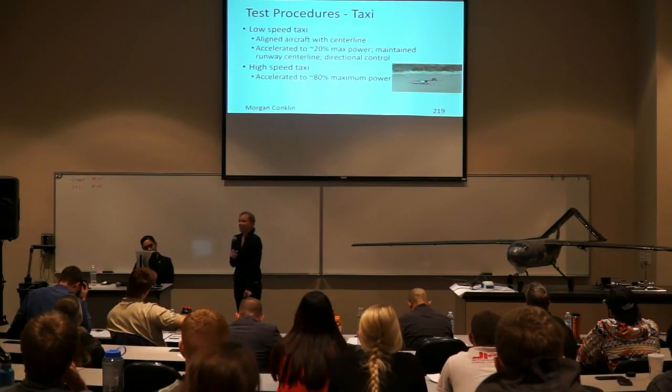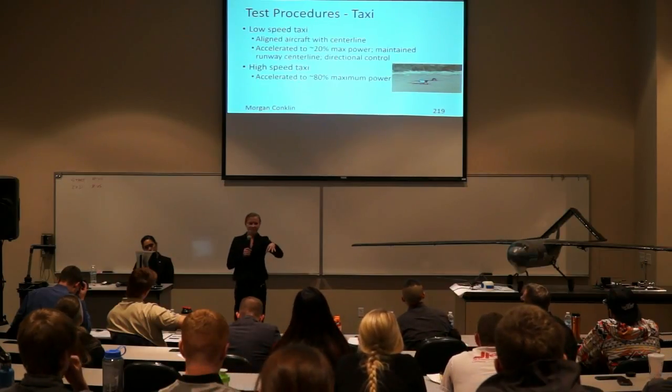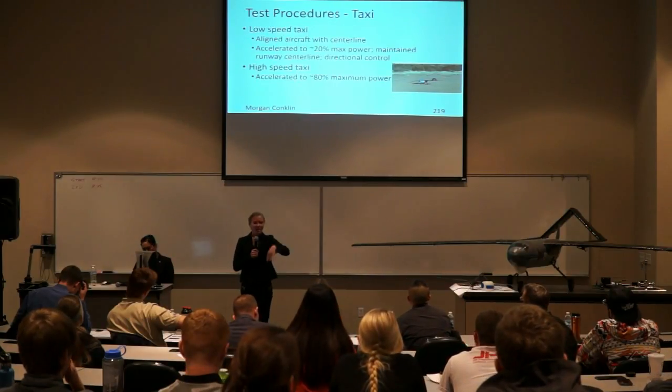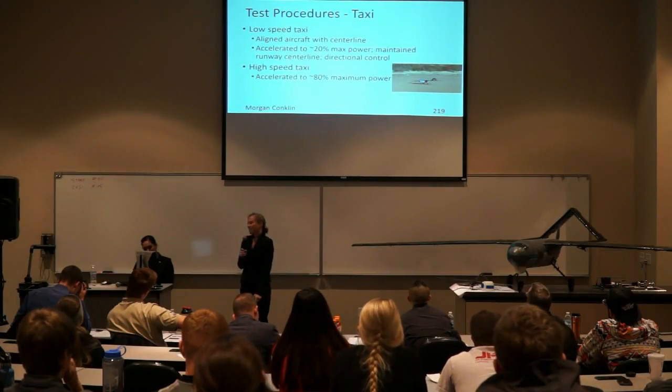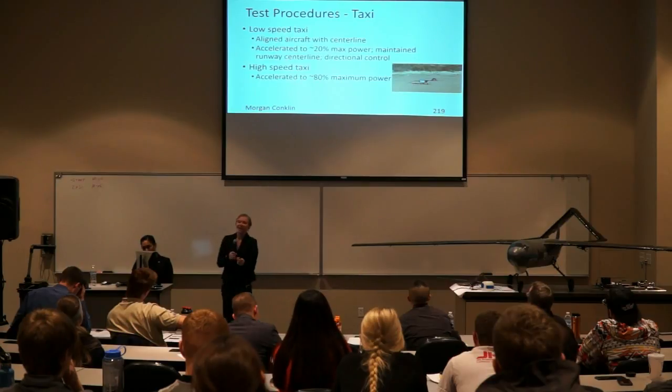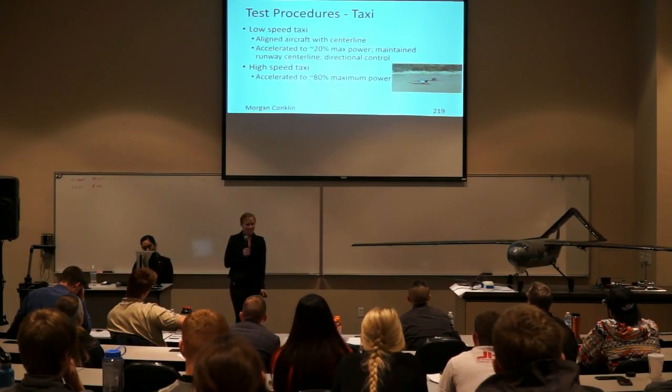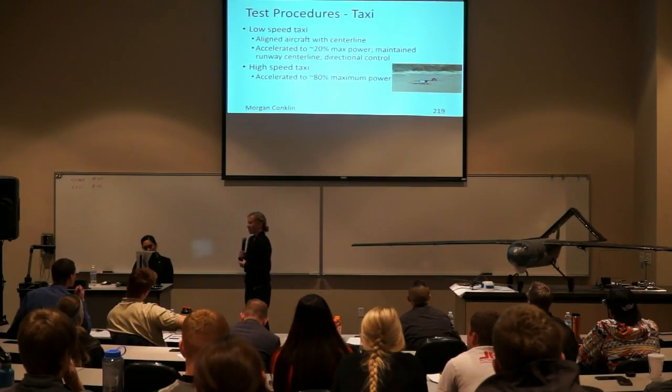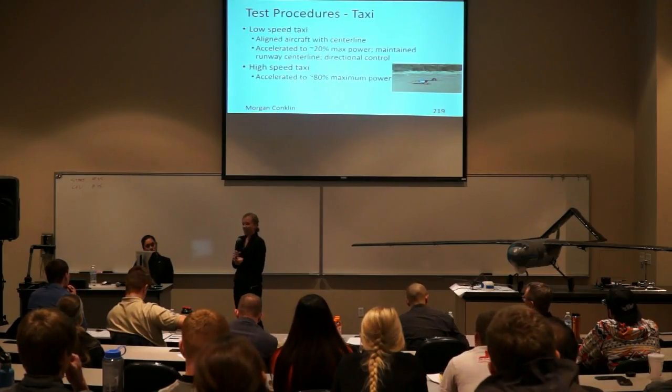For the low-speed taxi, we aligned with the center line of the runway and accelerated to 20% power. And we tried to maintain directional control as well as the runway, but we didn't have a center line on here. And we had a sensitive nose wheel, so we fixed that for flight test. For the high-speed taxi, we did the same thing, but at 80%.